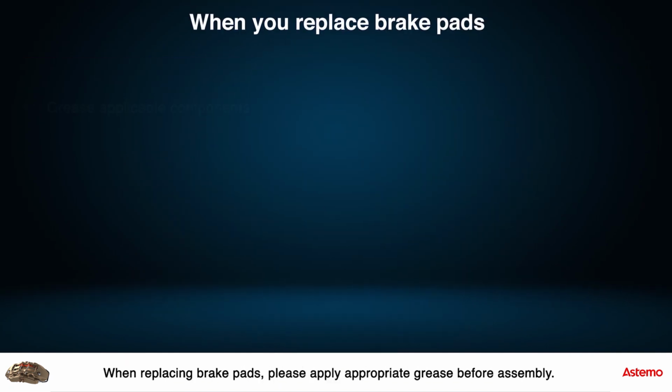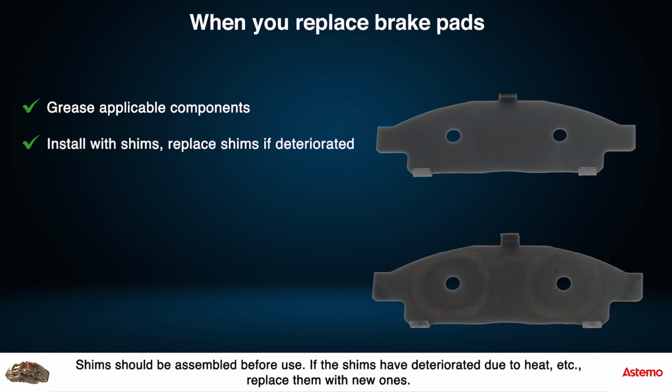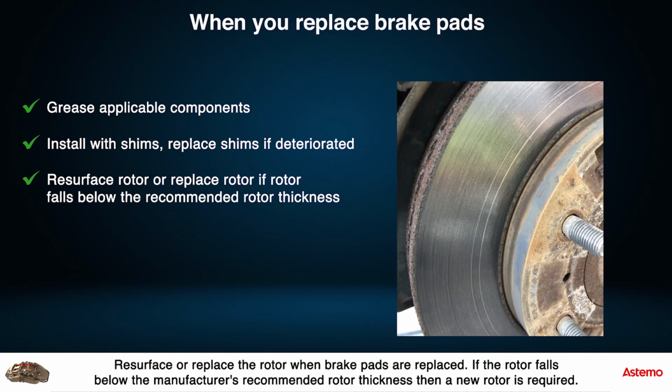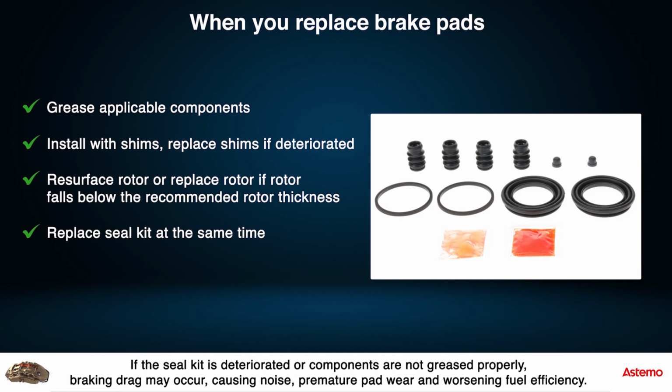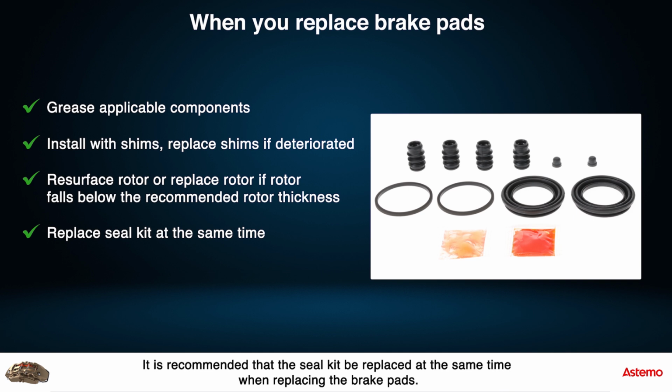When replacing brake pads, please apply appropriate grease before assembly. Shims should be assembled before use. If the shims have deteriorated due to heat, etc., replace them with new ones. Resurface or replace the rotor when brake pads are replaced. If the rotor falls below the manufacturer's recommended rotor thickness, then a new rotor is required. If the seal kit is deteriorated or components are not greased properly, braking drag may occur, causing noise, premature pad wear and worsening fuel efficiency. It is recommended that the seal kit be replaced at the same time when replacing the brake pads.